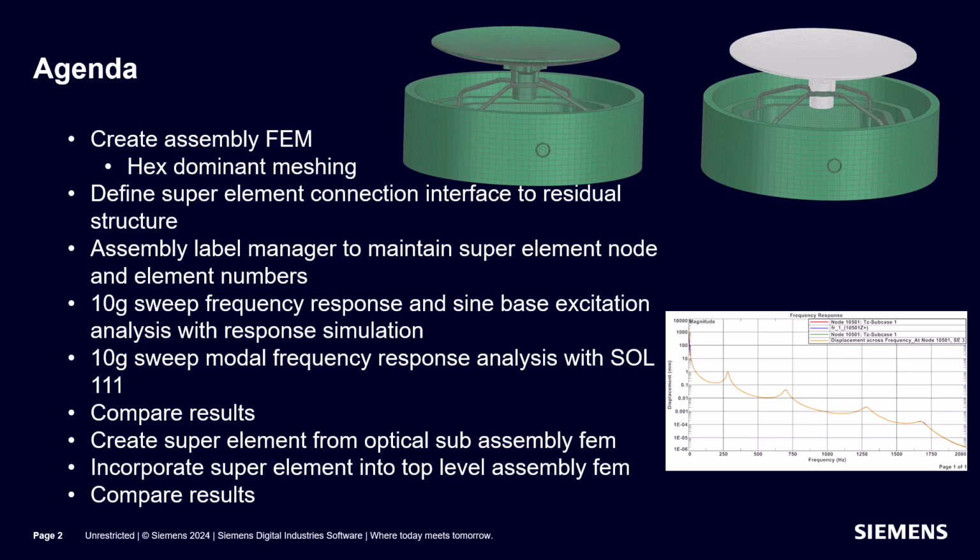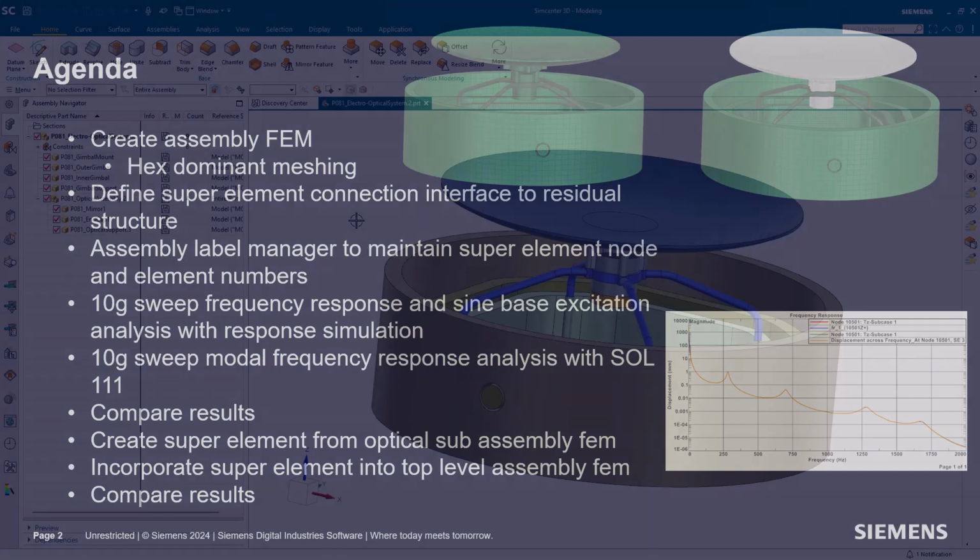As a baseline for comparison, we'll first use response simulation to create a frequency response analysis and a sine base excitation analysis. Since Response Sim doesn't support superelements, we'll create a Solution 111 modal frequency response analysis where we can incorporate superelements. Lastly, we'll compare results from all analyses.